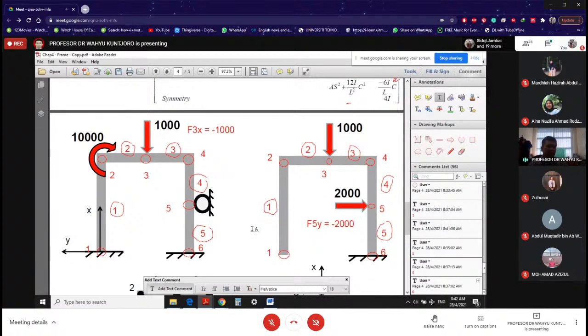What about this 10,000? This 10,000 M is actually minus 10,000. Unit can be Newton, meter, whatever. So I hope you understand why it is negative, because positive moment, no matter your x and y axis, is always going to be measured positive as counterclockwise and negative when it is clockwise. So I hope you see what's going on over here.